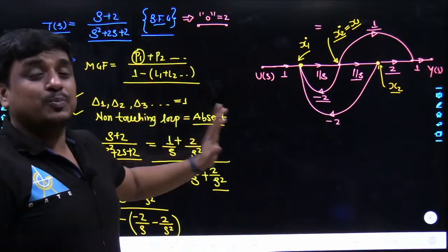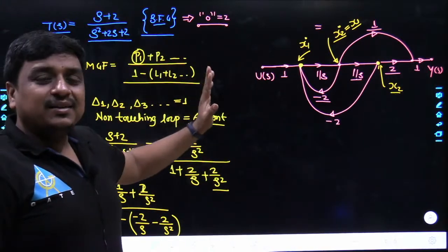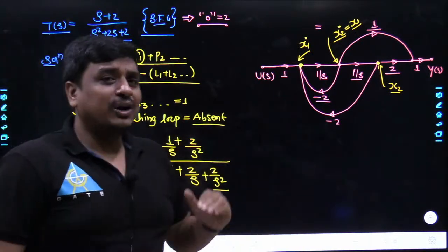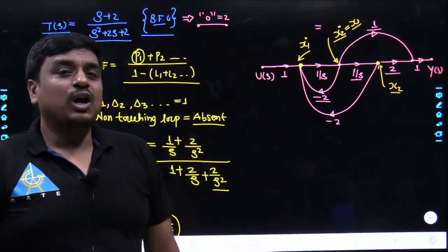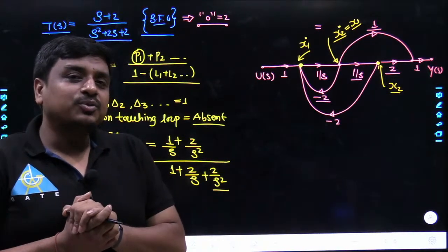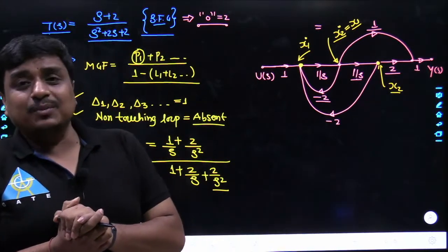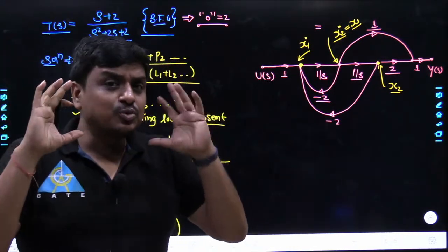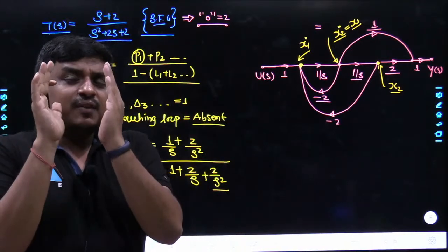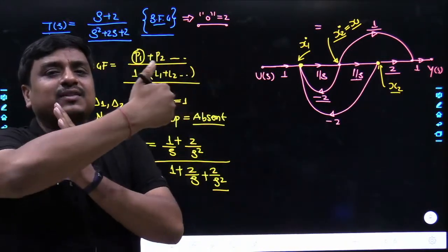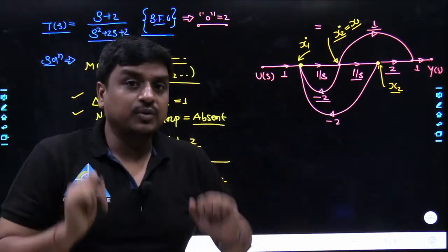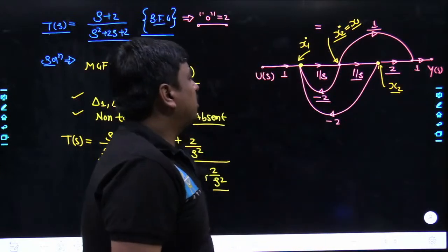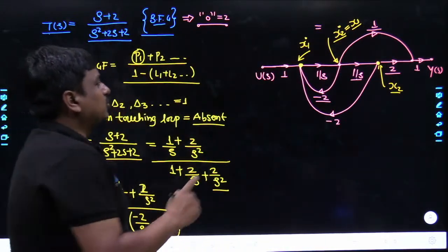Now it becomes much easier to dictate the x1 dot in terms of x1, x2 and u, and similarly x2 dot in terms of x1, x2 and u. Nobody should write x1 dot in terms of x2 dot, or x2 dot in terms of x1 dot. That's not permissible. If we talk about the first equation, which used to be the state equation, the derivative of the state variable has to be dependent over the state variables itself or the inputs, or including both. That is why a little bit of change has been accommodated. Agreed? So let me focus over the first one.